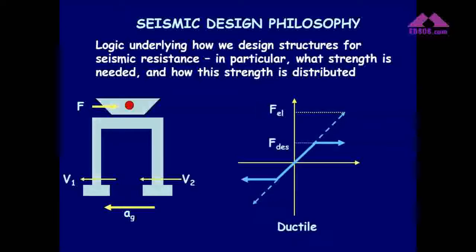civil engineers. What we do instead, we do ductile design. In nearly 90%, 95%, 99% of the buildings, when you look around where you live, these buildings are designed with ductile design philosophy. What I mean, yes, during an earthquake action, seismic excitation, the elastic seismic forces act on the building. What we do is to reduce these forces to a level, and we design our structure for this reduced amount.